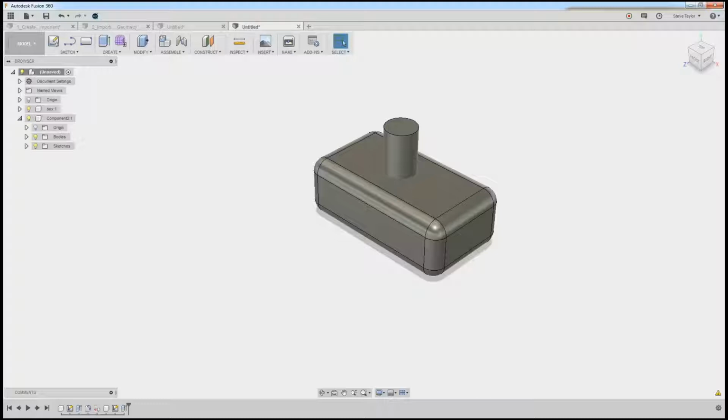If you're in a hurry and forget about rule 1 and forget to create components at the beginning, you can go back later and tidy up your design. If you're creating a design that does not have joints and everything is stuck in place, maybe a jewelry box with some feature panels just stuck to it, you might find that just using bodies is fine for your design. If it's got moving joints, then you need to use components.